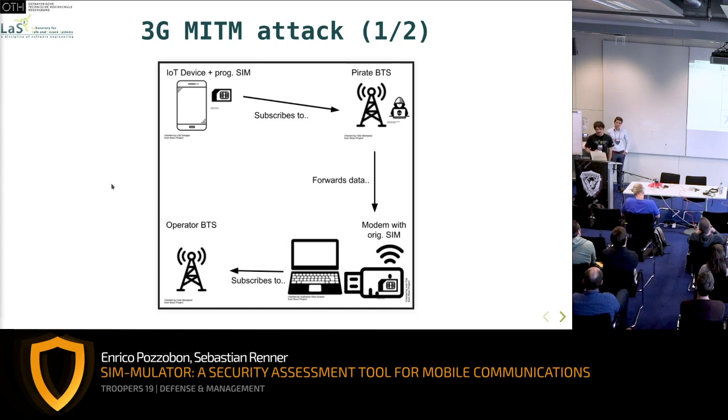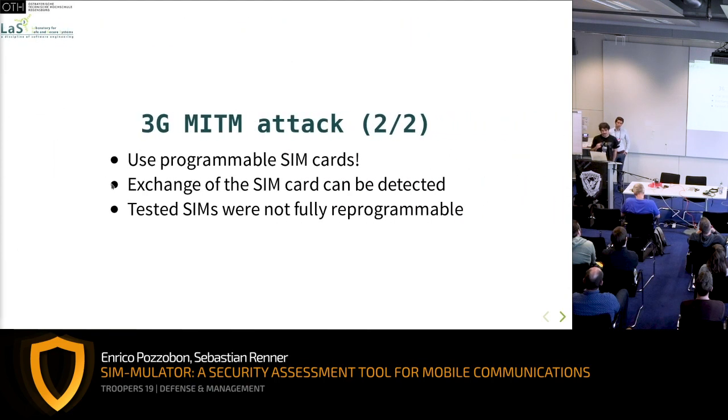However, on an IoT device which comes with an embedded SIM card out of the box, sometimes replacing a SIM card is not possible. Not because the SIM card is soldered on the board, because that's just a matter of desoldering it and replacing it with wires, but because the SIM card contains some specific files in the file structure that can be verified, and the modem or the device will detect in some way that the SIM card has been replaced, and it will refuse to connect.